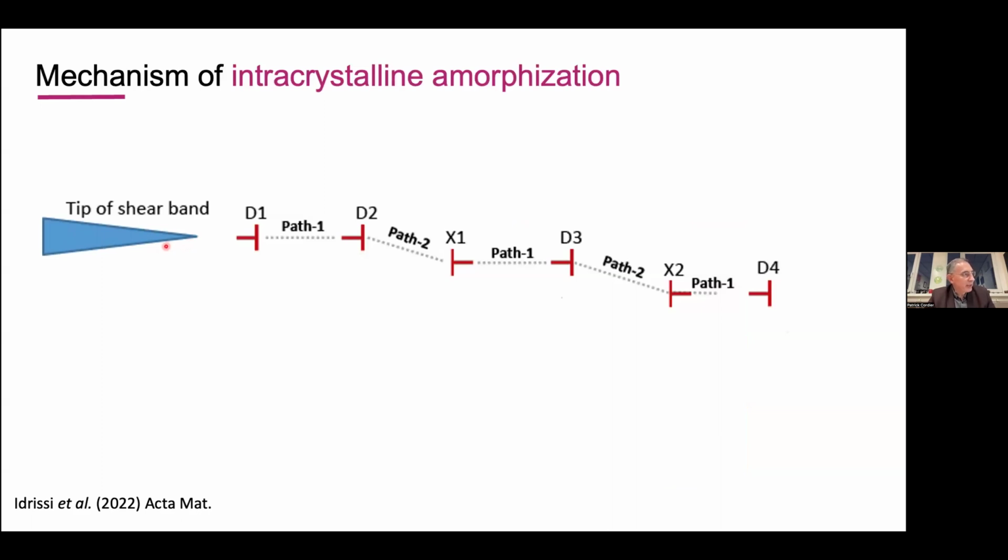So this is the idea that we have about this process. You know, this lamella is progressing like that, is moving to the right. Ahead of the tip, there is a lot of stress, very high stress, high enough that dislocations are nucleated ex nihilo. And then, you know, you have a feedback. The stress field of the dislocation guides the propagation of the lamella, which follows the path of the dislocation. And this is probably the reason of this zigzag that we see. Okay, so this is what we inferred from the experiments performed by Sylvie de Mouchy.